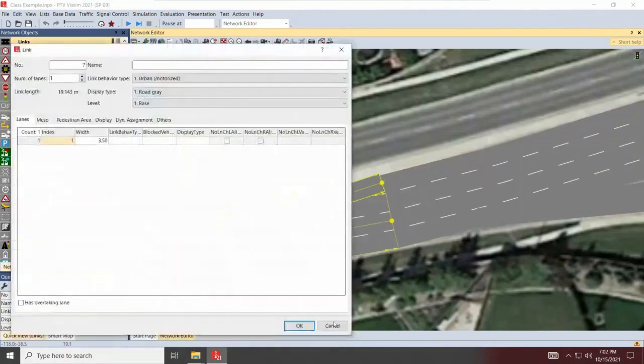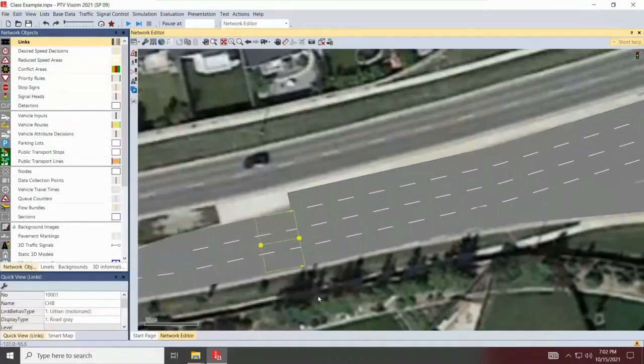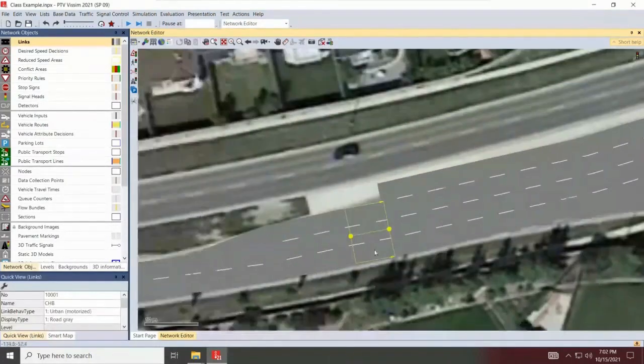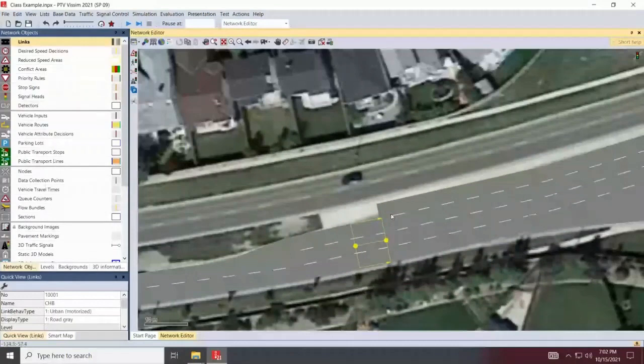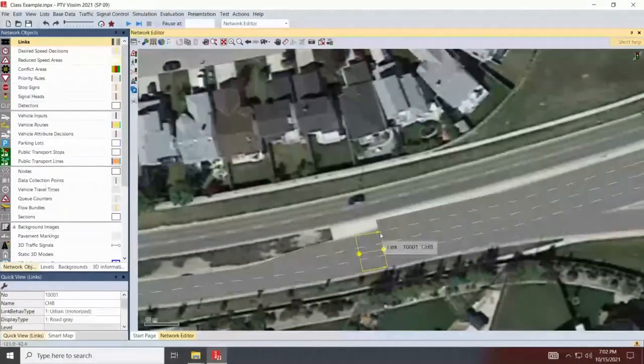To be honest, I'm sorry, I'll undo this actually. Because in this case, if you recall, traffic will already be in its appropriate lane, and the movement is going to happen from the 2 most left turn storage lanes. In that case, having that extra bit of dead space does not hurt, because that's what vehicles will use to get into the right lanes. So I'll keep it that way.